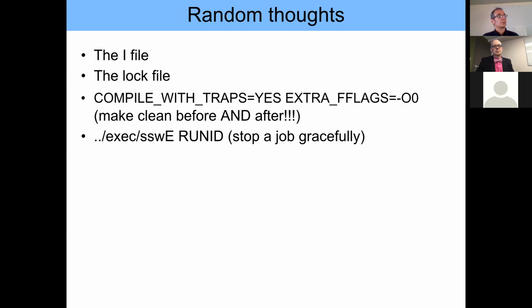And this file is there for safety, because as the model is running, you might do something, I don't know, you are tired or you're just thinking something else, and you try to run the exact same model in the exact same directory. This log file will protect you from overwriting what you're actually doing. And the caveat is that if your model for whatever reason crashes, this log file survives.